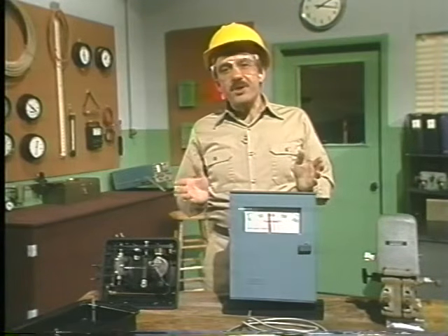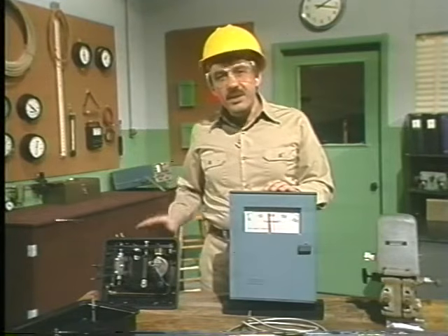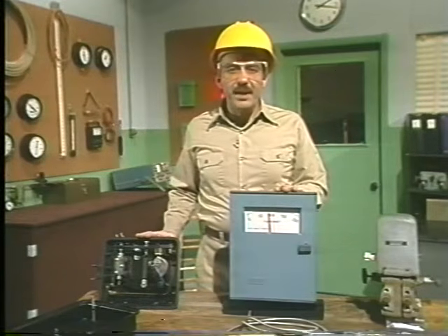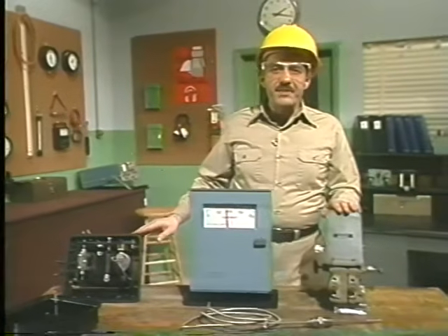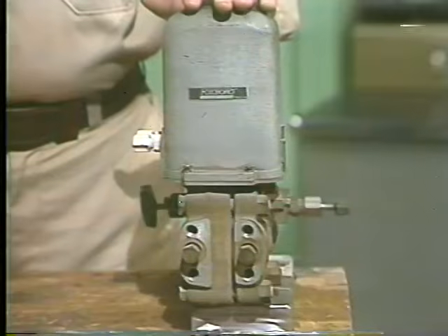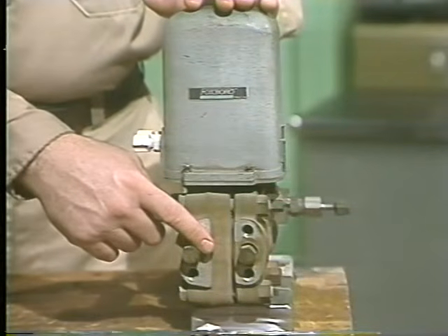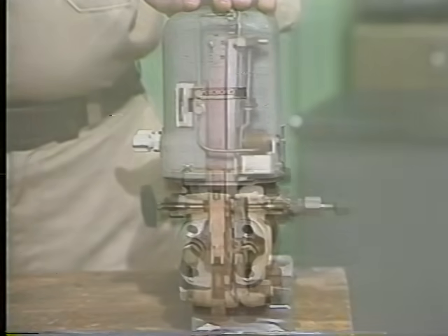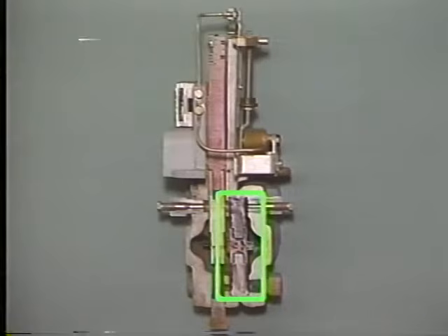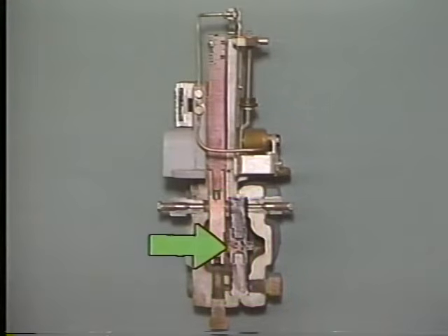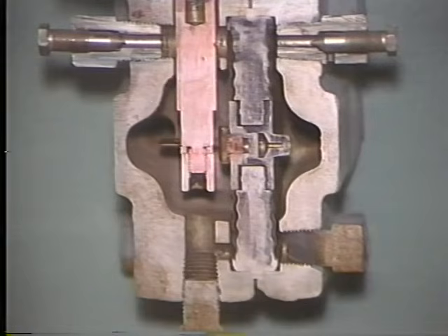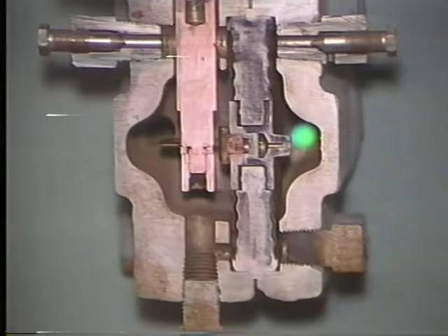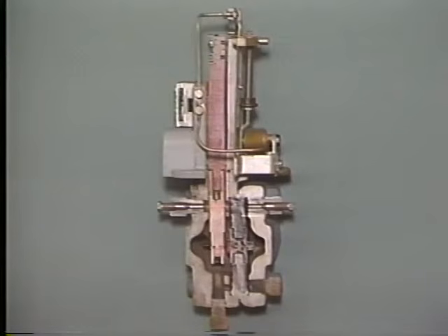So we've seen 2 different input mechanisms, one that uses a bellows and one that uses a Bourdon tube. Now, this differential pressure transmitter uses still another kind of input device, a type of diaphragm, which is encased in this housing. We'll use a cutaway of this device to identify the internal parts. The diaphragm here senses changes in differential pressure between a high pressure and a low pressure. The high pressure is conveyed to one side of the diaphragm through this port, and the low pressure is conveyed to the other side of the diaphragm through this port. We can see how this works using a simple illustration.